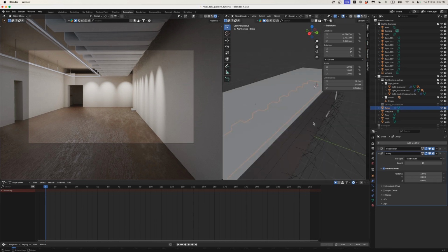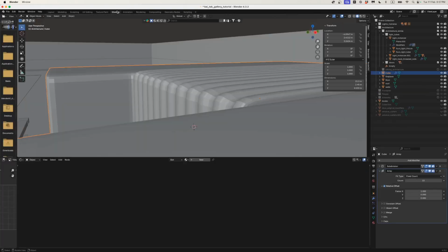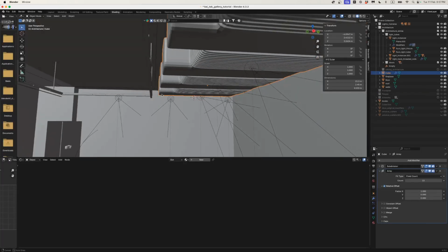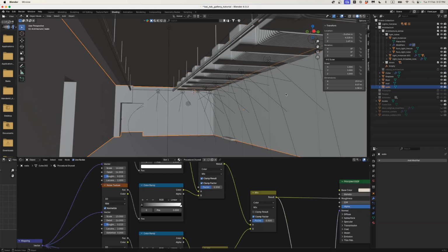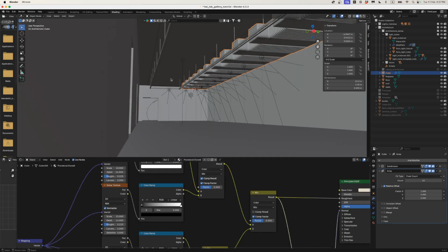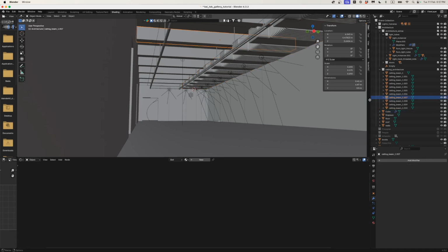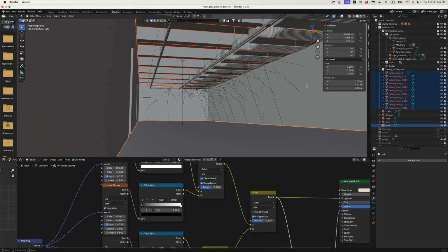If I press backslash, and so let's just go into our shading and put the right shader on it. So the shader we have on the walls is called procedural drywall. I'll just put that on it. Just type in P, there it is. And I'll do the same for my beams. All of these, I can shift select them, and we can do this trick of shift selecting the wall and just press Command L and link materials.